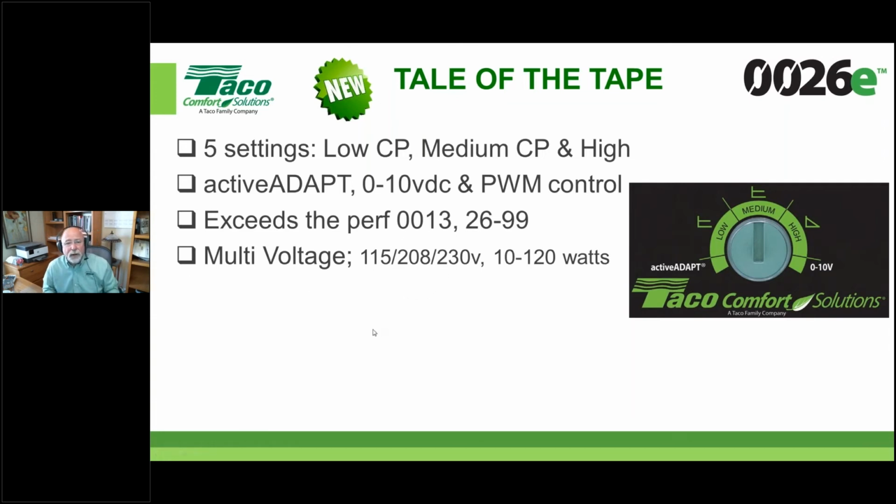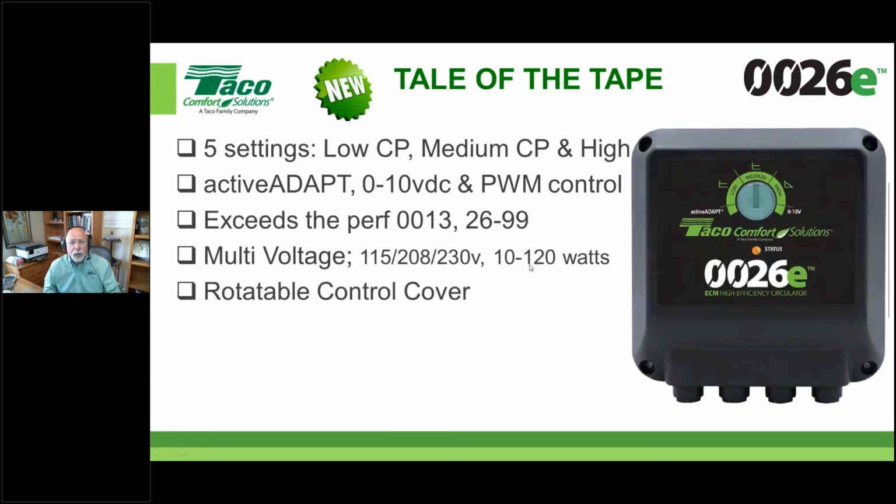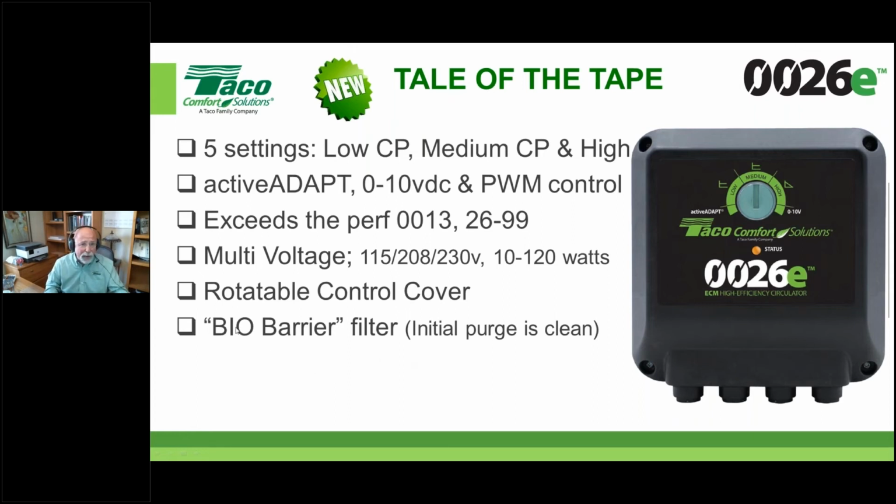Cool thing about this pump, any voltage you want up to 230, folks. So 115 to 230 with one SKU. The wattage consumption goes down to 10 and only up to 120 watts, okay? The cover, you notice how I rotated that, bringing it in. Just 4 screws here. It's got a little flexible ribbon, and we can spin that thing any direction we need so it doesn't look goofy on its side. If people want to pump left to right and not up and down, a lot of times these things will get installed and we just say, hey, you could have flipped that. It's pretty easy.